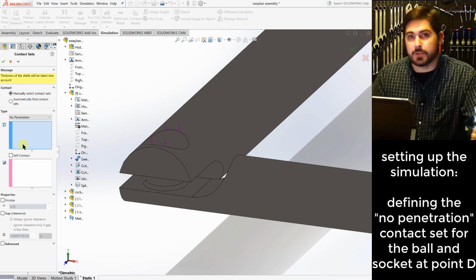They're very easy to use as long as you have defined all of your geometry correctly, because they are actually trying to compute what would really happen if a real part with these properties really interacted with another part, and it tries to figure out those contact forces and stresses and that kind of thing. What you do is you can pick this no penetration. That's what I'll most of the time use for this. It's basically saying this part's not allowed to penetrate the other part.